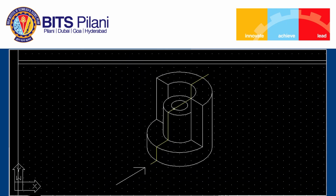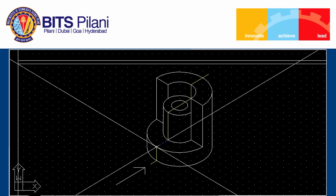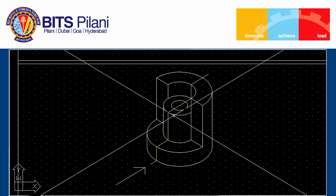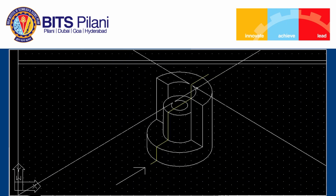For this cylindrical surface which is seen here, it has diameter, outer curved surface 4 grid space, inner 2 grid space. So, radius is 2 and 1 respectively. Height, when I want to find out, I will move only along the height dimension. For example, here 1, 2 grid space is height. For this cylindrical portion 1, 2, 3, 4 and remaining part 1, 2. So, 2 plus 4 plus 2, total height is 8 grid space.